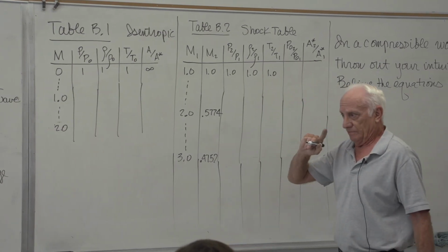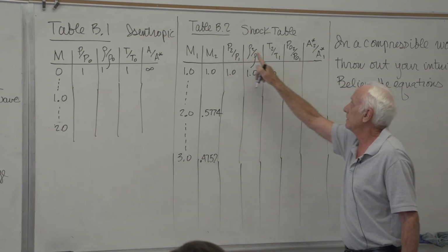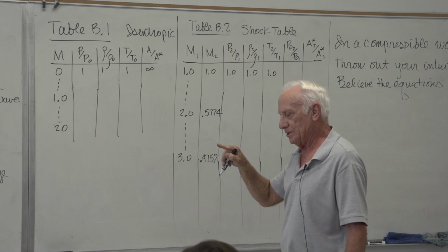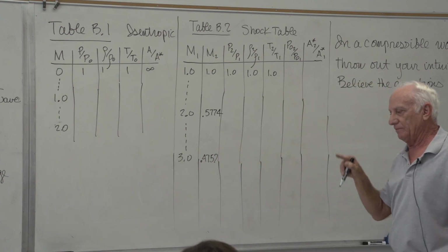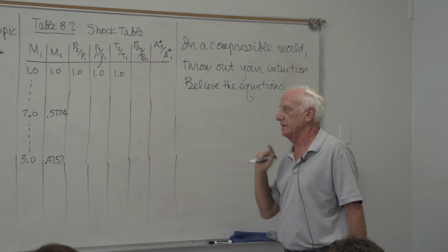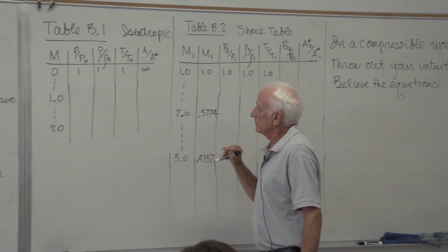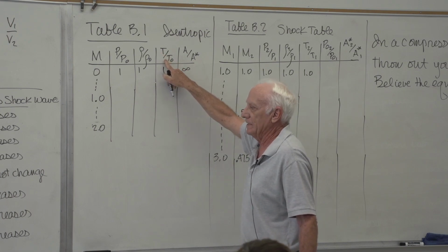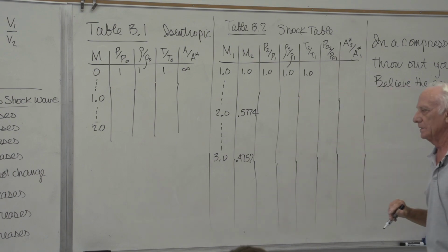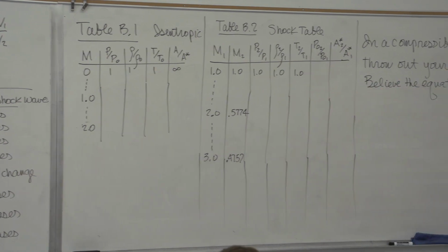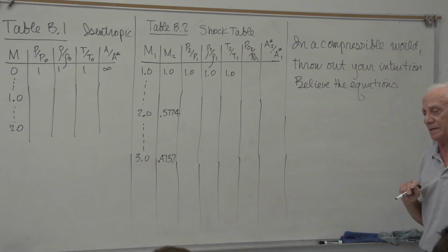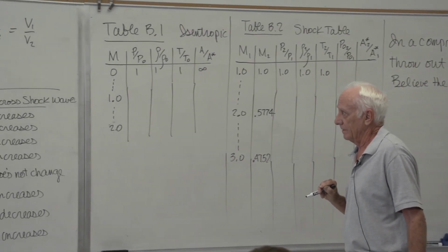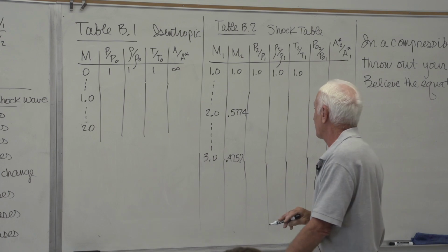Now, just so you remember from your first fluids course, this is the static pressure. This is the stagnation pressure. What's the stagnation pressure? The pressure at a point in a flow field where the velocity of the fluid comes to rest isentropically. Okay. T naught. T, no subscript. Static temperature, T naught, stagnation temperature. Stagnation temperature on a reentry nose cone where the velocity comes to rest. Do you think it gets hot there? Oh, you better believe it gets hot there. It gets really hot there, okay, because of friction. Even without that, bring it to a rest without friction, it's still hot.